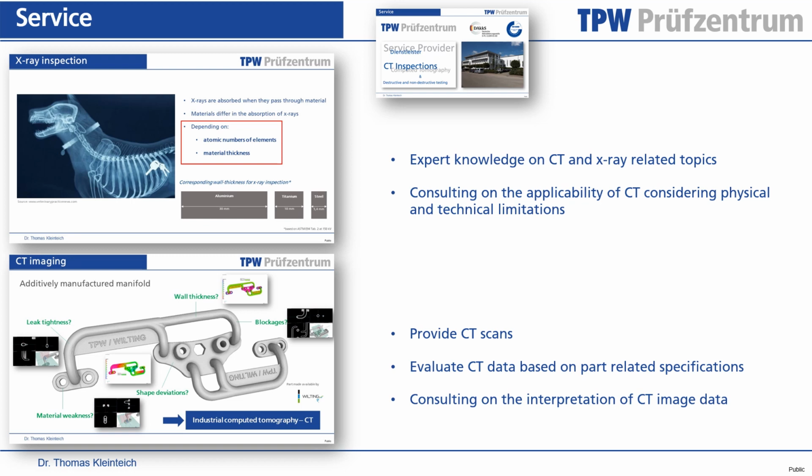And of course we also do the CT scans. In case you can provide us with a clear specification on what would be okay or not okay for your part, we can also evaluate this CT data and give a report with the part and say it's okay, it's within specification, or you can say it's not okay, it's out of specification.